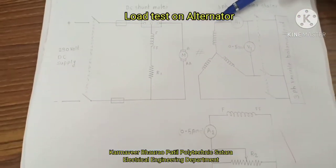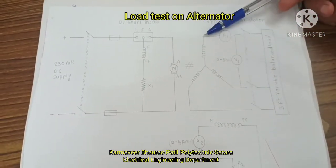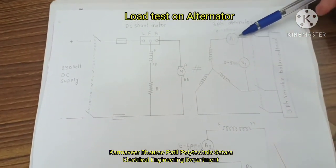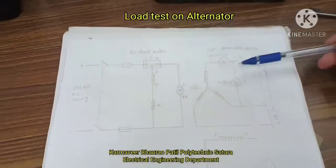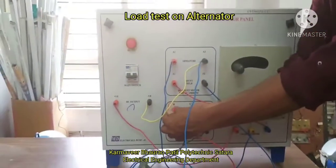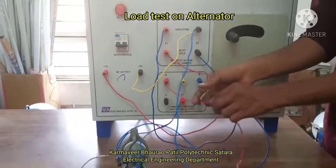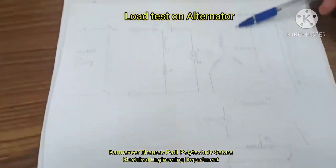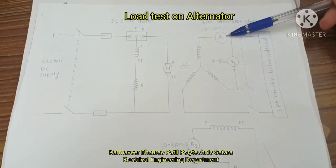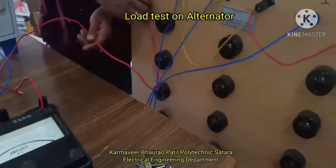You will be having three stator terminals R, Y and B. From the R terminal we will be connecting an AC ammeter, which will measure load current. So the R terminal will be connected to the common of the ammeter. The second terminal of the ammeter should go to the R phase of the starter load.